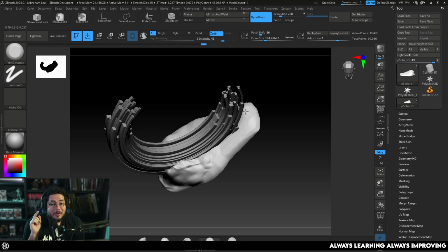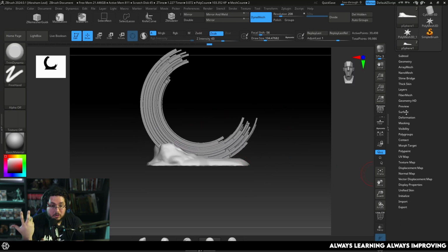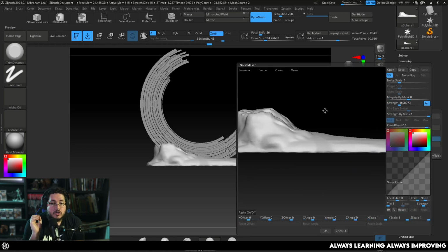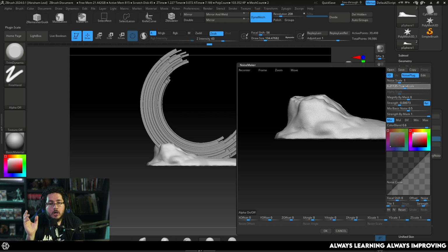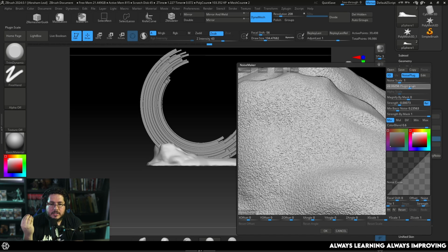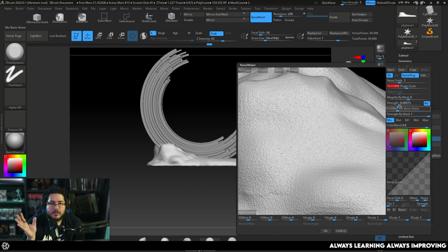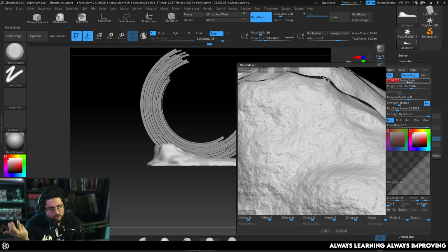Now here, I'm about to show you a very cool trick, which is how to add detail without having to do a lot of work. And this is by using something called surface noise. If we go to the Surface Noise palette on the left side of the element, you're going to be able to select this Granite option. By modifying some of the sliders in the noise section, you're going to be able to tweak how much noise you want to introduce to this asset. You can see there on the little preview how we're getting this very interesting noise effect on most of the surface. Now make sure to bring the noise scale all the way down so that you're only getting the noise from the plugin and not extra noise from ZBrush.